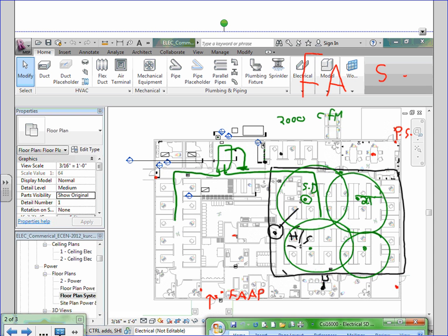I'm going to make an executive decision. And so you need one duct smoke detector, and it's going to be, yep, if you want to draw it in there, yours will be better than mine, in the return duct of the unit inside the mechanical room.